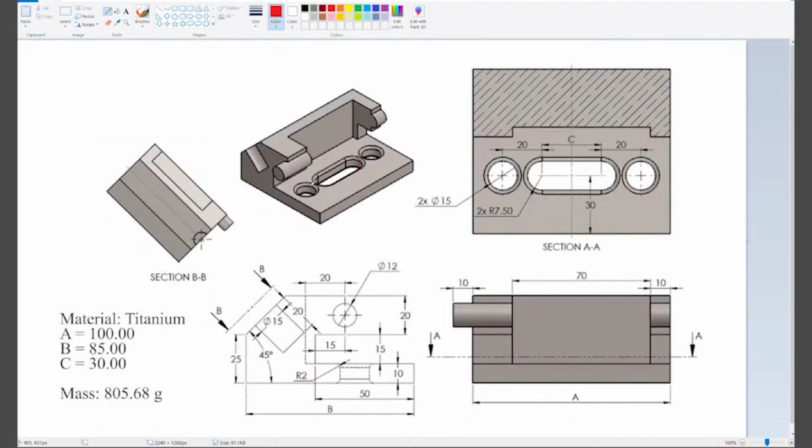Some other things, these will be hole extrusions, just regular extrusions for this 3D part. You might have to make this side view, extrude that, and then make holes or extra sketches to make this cylinder, for example.